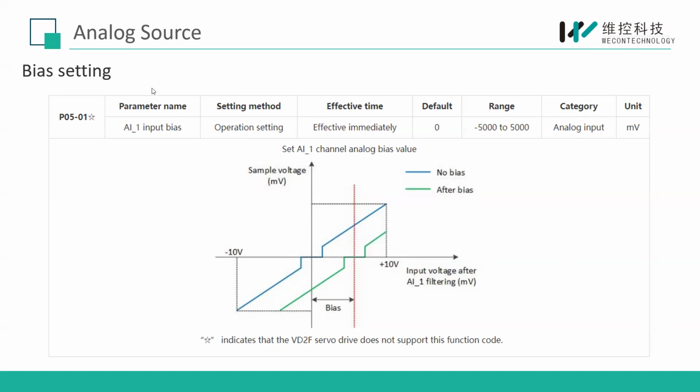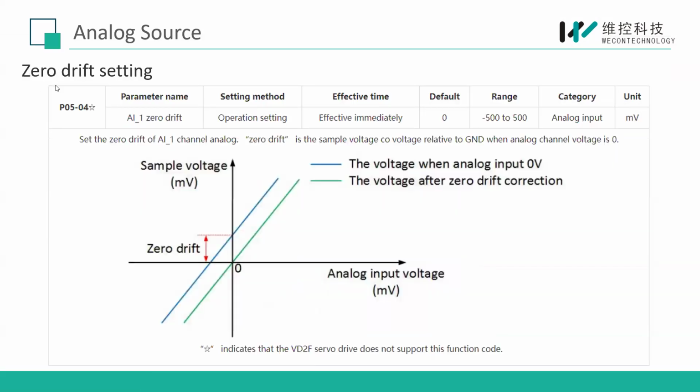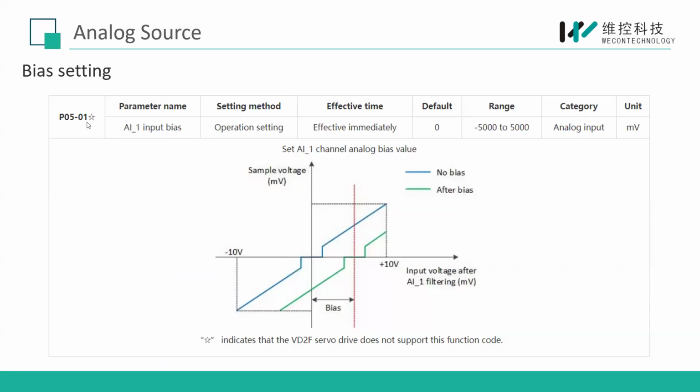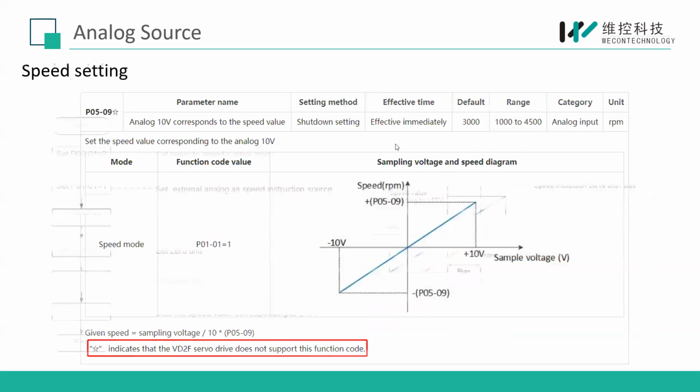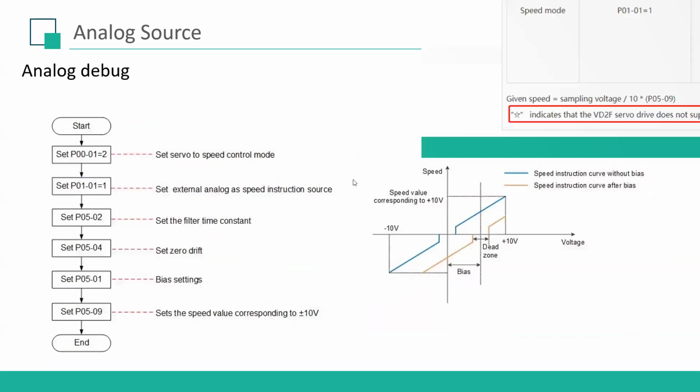Yes, so this is how to set this parameter. Just one point to note: we need to first set P5-4 first, and then we set P5-1. We can't change the order, otherwise the setting will be wrong.